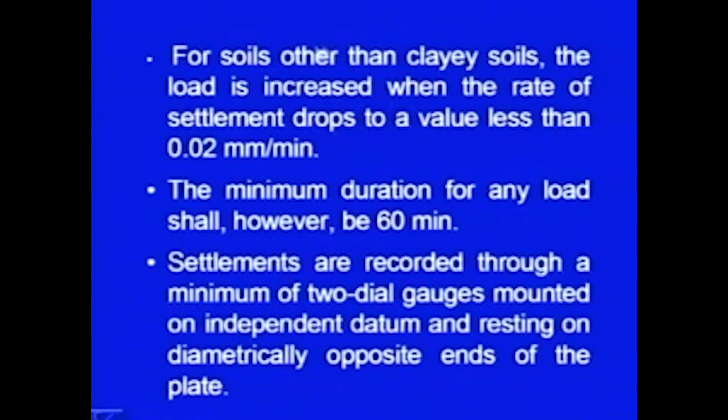So, in case of the clay soil, it may take a lot of time, and as we discussed earlier, around 70 to 80% of that probable settlement should have occurred. And if it is a sandy soil, in case of the cohesion-less soils, it takes less time. So, we will be observing the settlement rate, and when it is less than this, we take the next incremental loading.